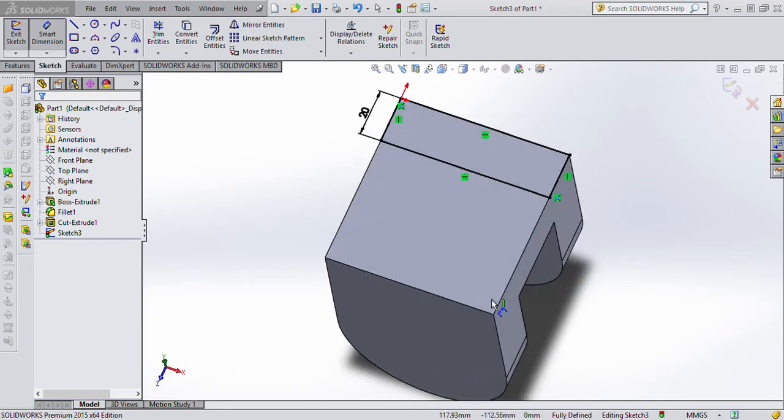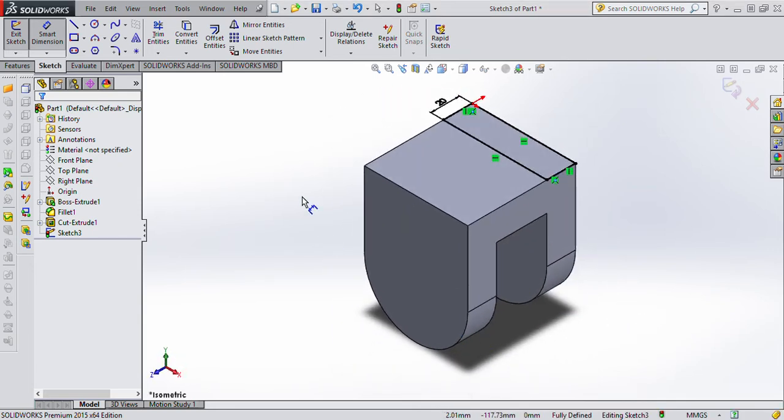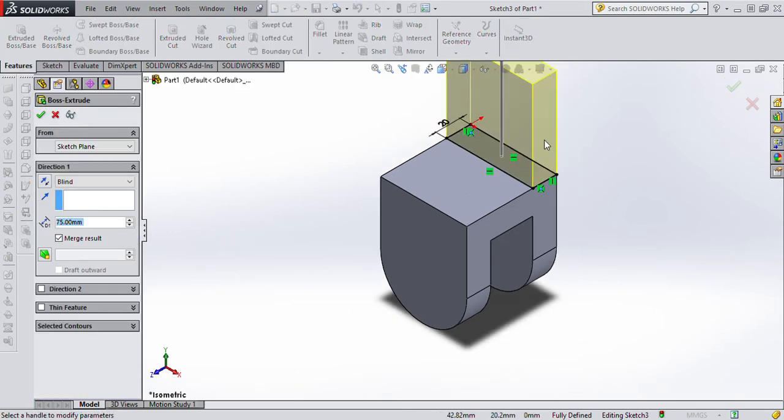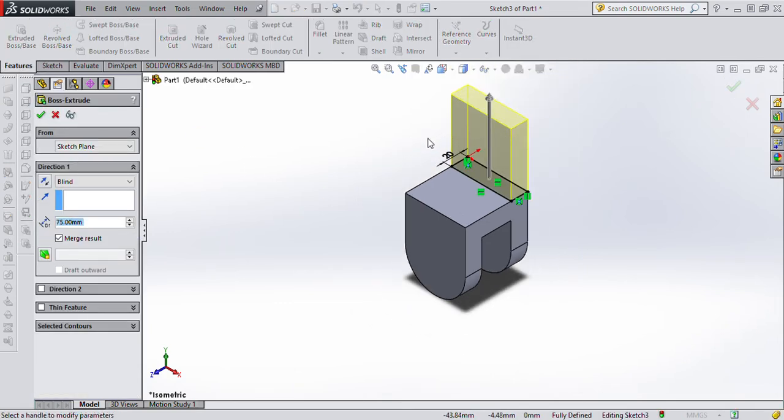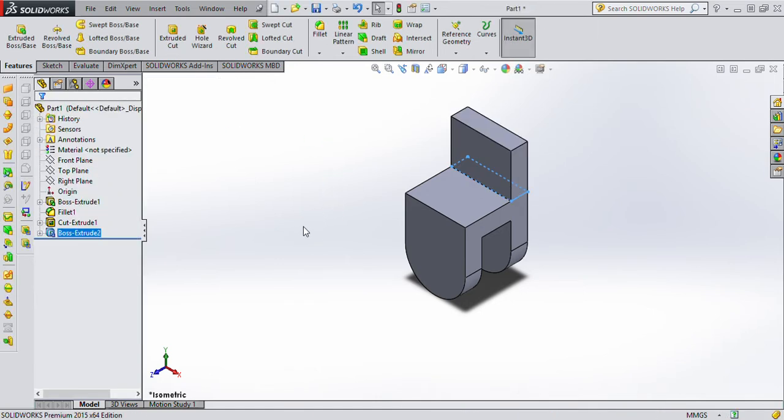Isometric. Now I'm going to extrude this part, but when I'm looking at this, I have 30. Let's say that I have to make some calculations because definitely the paper will be shared with you. This one is number 13 in your paper. Okay, 74 minus 52 plus actually 30, it is 52. Okay, you have to extrude by 52, confirm.